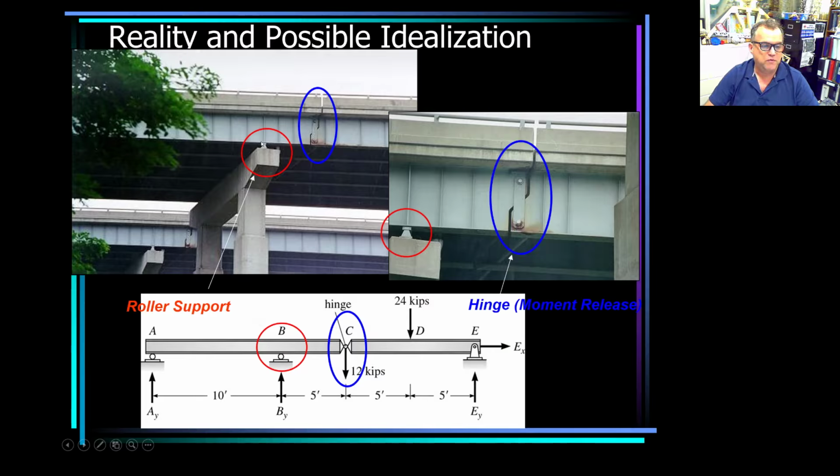Okay, what type of support will that be? Let me give you a clue. Yeah, a roller. It's a rocker actually, but yes, roller support. Now, what is this thing here? This thing here is a hinge. The difference between the hinge and a pin, for example, which there are pins somewhere over there, probably holding it, is that the hinge, which is this one, produces two reactions also, let's say horizontal and vertical reactions.